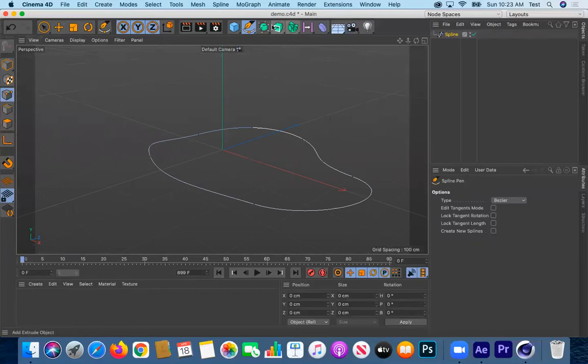So let's get into some of these tools here. If I'm using this spline tool, now you see I have a spline that's been added as an object to my object list. Let me go here, and this first tool is called Extrude. I have Extrude, Lathe, Loft, and Sweep, and these are all ways that I can generate 3D object forms, primitive objects from that spline.